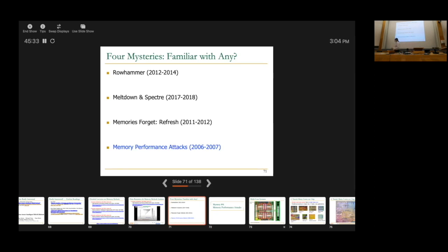So exactly, that's another different thinking, basically. Today, we refresh the entire chip because the memory controller doesn't know which memory is allocated or not. And that's a very good, another question, right, basically. If memory is not allocated, why are we refreshing it today? It should not be done. The problem is today, this information, whether a piece of memory is allocated, is not communicated to the memory controller. Even though the operating system knows it, it doesn't communicate this information because there are no communication channels. But if it's communicated, you can fix that problem also.